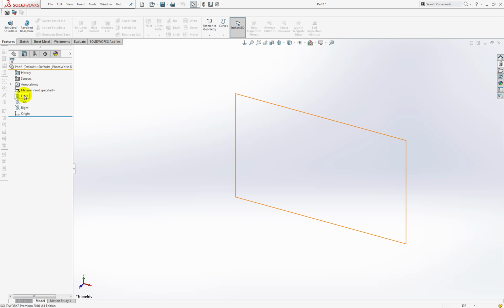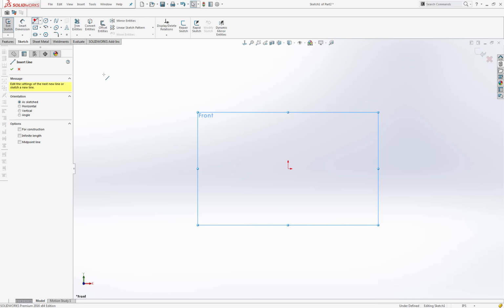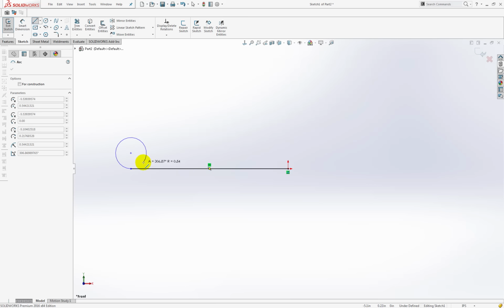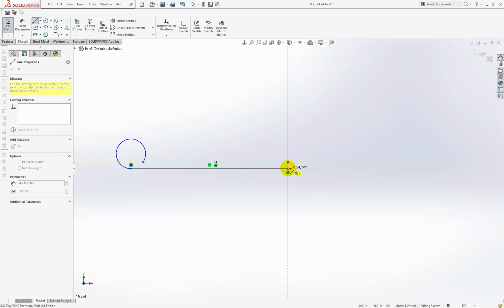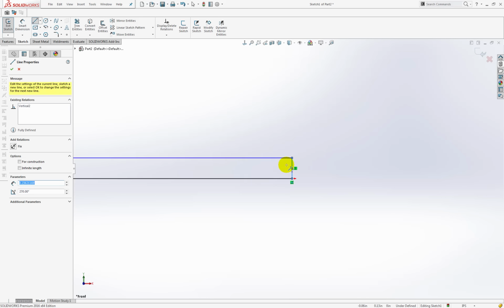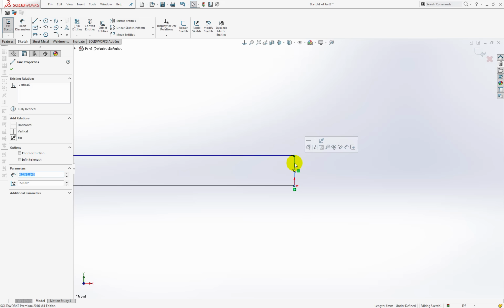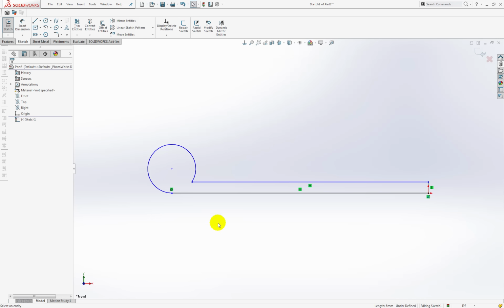So I'm going to insert a sketch on the front plane and just start with a line. Just drag that endpoint over. When I pull away from the endpoint and come back, it becomes an arc. So I'm going to draw that outside perimeter crust and then close that profile. I'm going to make that vertical entity a construction line and then hit the F key to fit to window,